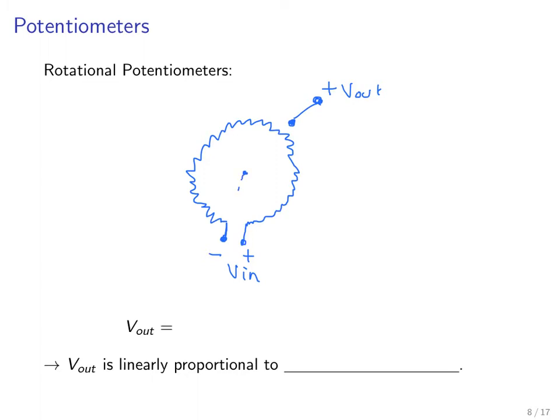Of course, the potentiometer can't close all the way perfectly to 2 pi, since you have to have some gap between the terminals so they don't touch each other. So in this, the wiper will be at some given angular position theta, while the maximum possible rotation will be some other angle theta max, which will be slightly less than 2 pi. So we have to think about now the circumference if we're trying to calculate the total resistance.